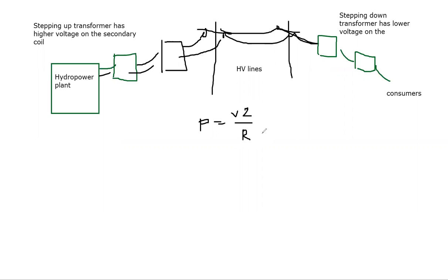Yeah. So the smaller the R, the more power you can transfer. But you're limited in how much R can be. So how can you transfer more power? You have to increase the voltage. But if you increase voltage, then you have to decrease the current.